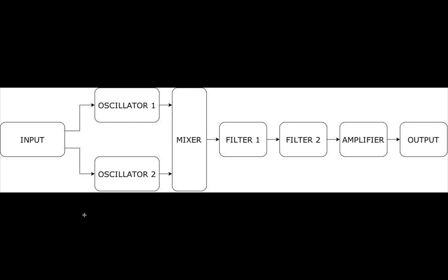That's where you do your initial sound shaping. But then the difference is it moves on to another filter. And what we call this setup is two filters in series, which means one after the other. So your signal passes into one filter, the sound is shaped by that first filter, and then that finished shaped sound is moved on to the next filter, where you can do some more shaping. And then it goes on to the amplifier and the output like it does before.